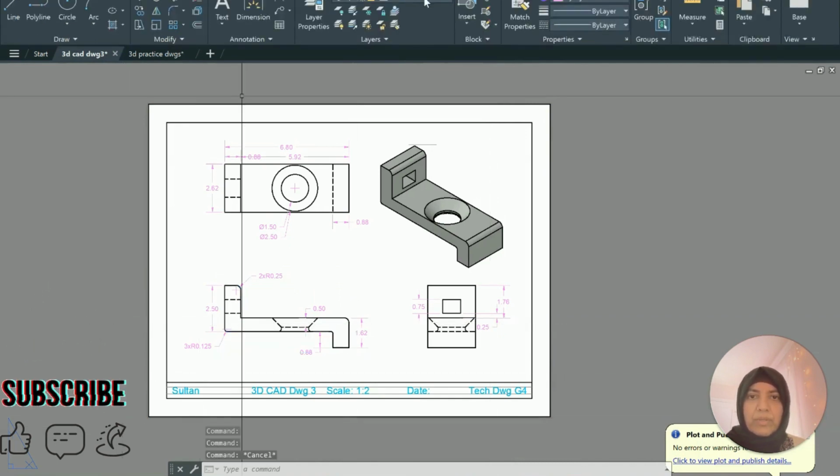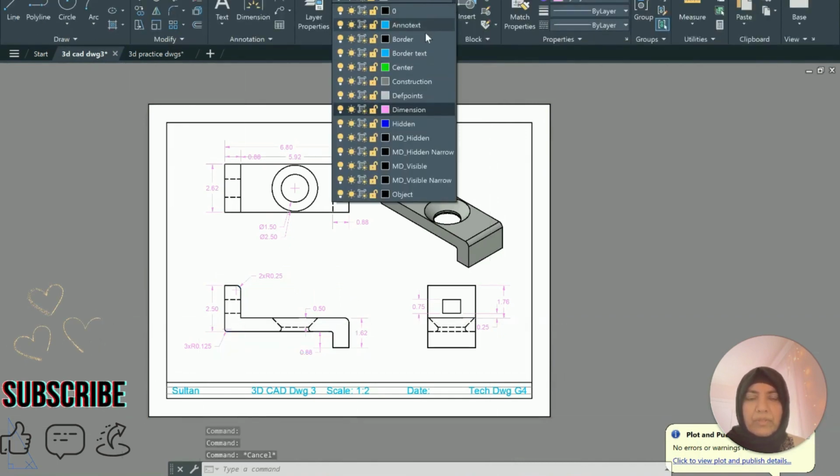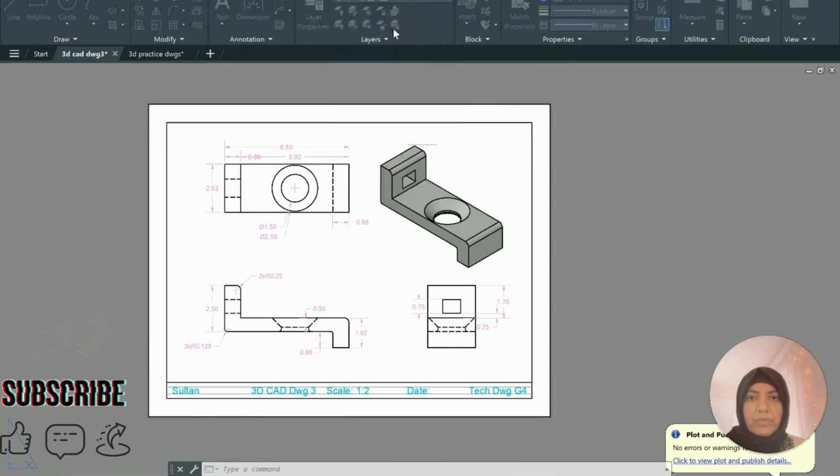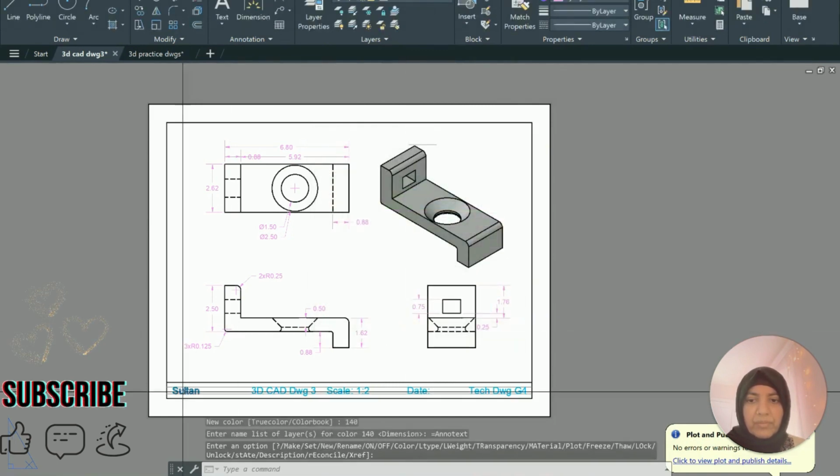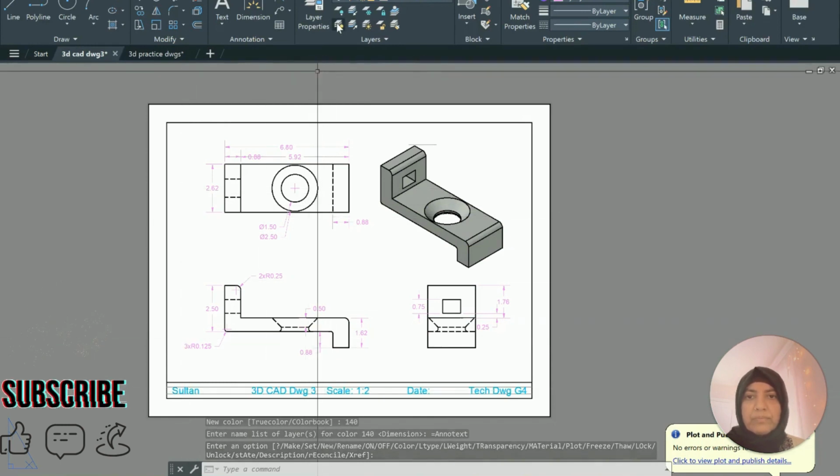And the last thing is the annotation text. This layer also, the color for that I changed to 140, and the border text also is 140.